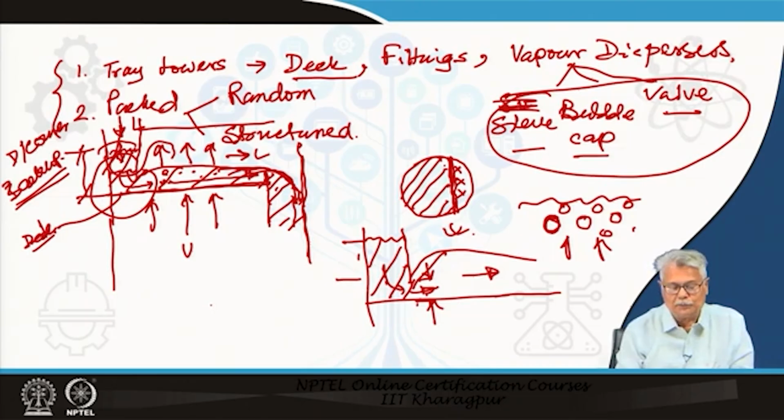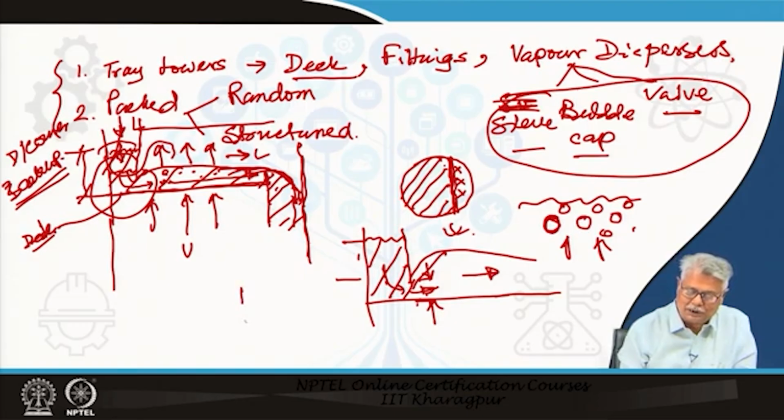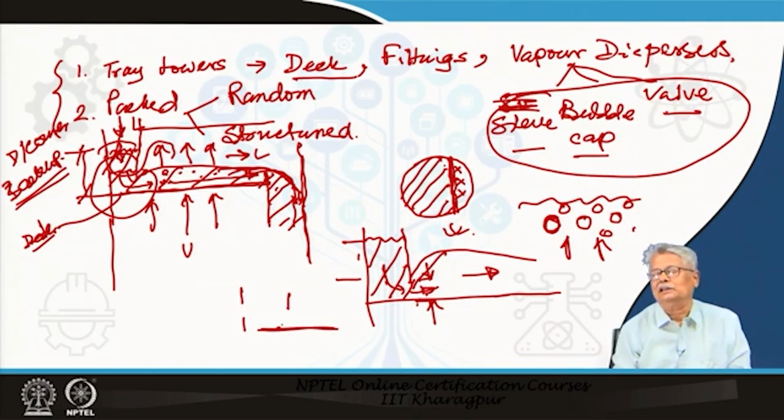So, one thing is true, that if I somehow have a very low liquid level or very low liquid flow in my column, the resistance, even with a small downcomer clearance, typically such clearance in industrial columns are never below 4 millimeters. No dimension in industrial column should ever be below 4 millimeters, 3 to 4 millimeters usually.